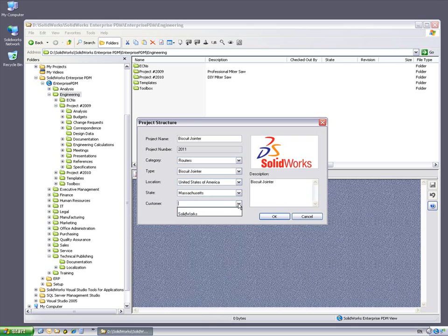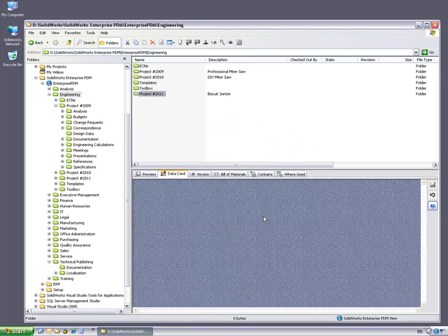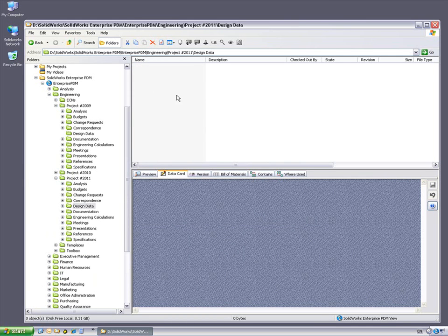For rapid implementation, these templates and data cards are built using a visual drag and drop environment, the lists being generated by SolidWorks Enterprise PDM or by your ERP system. The project template builds a standard set of directories ready for use. Document templates allow the creation of empty documents in advance to create virtual product structures.